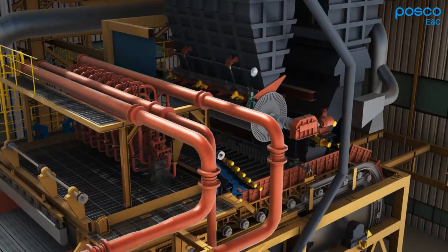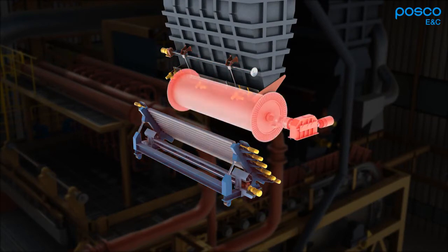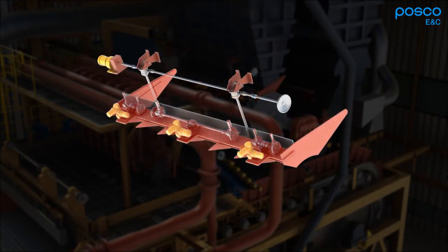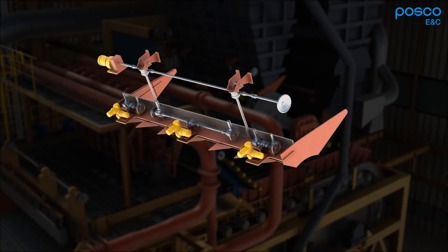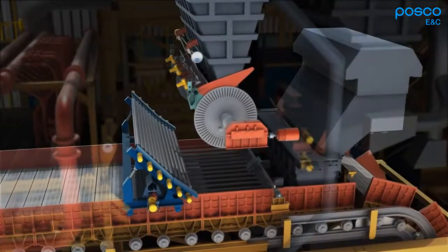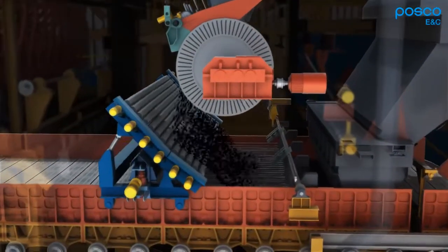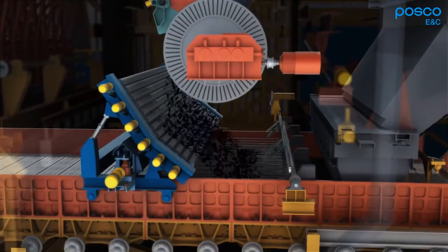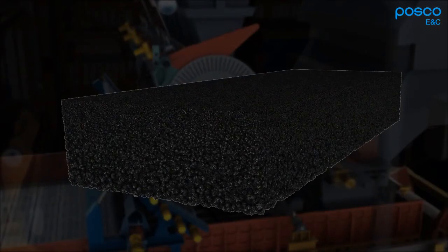There is charging equipment at the bottom of the surge hopper, and it consists of gates, a drum feeder, and a deflector. The gates consist of one main gate for controlling discharge rate and 3 sub-gates for feeding the materials evenly in the width direction to charge uniformly. Depending on the operating conditions, the opening of the gates and the rotation speed of the drum feeder can be adjusted, and the rotation speed of the drum feeder is automatically controlled according to the sinter machine speed and the thickness of the charged materials.